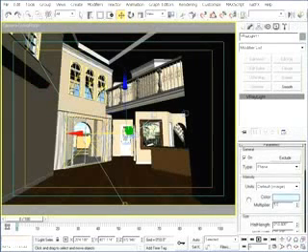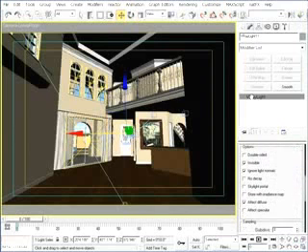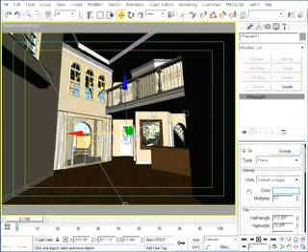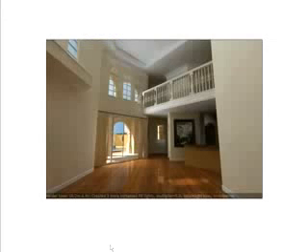And for this light, I assigned an intensity multiplier of 5 again. Since I already turned off the effect specular for the last light that I created, it's automatically disabled for any new light that I create like this one. And when I render, my rendering changes from this to this.